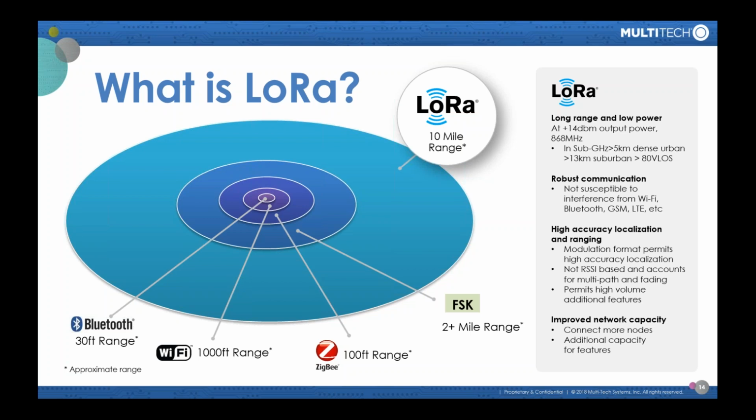It operates on the ISM band around the world. So those bands are free. They are unlicensed, so they're free to operate on. The bands are different around the world. In North America, you have 915, which is really operating at 902 to 928 megahertz. Europe has a range called 868, and the range I think is 863 to 870. It's somewhere very close to that.